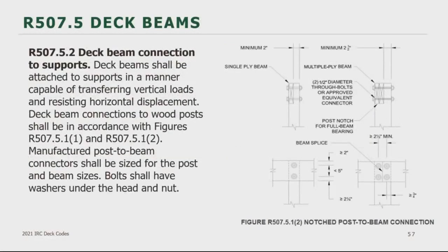Figures R507.5.1 parent 1 and R507.5.1 parent 2 provide details on how a beam is required to be connected to a notched post. Also note that bolts are required to have washers under both the head and the nut.